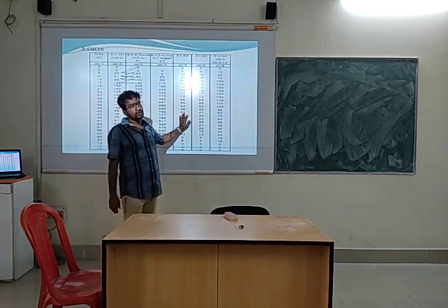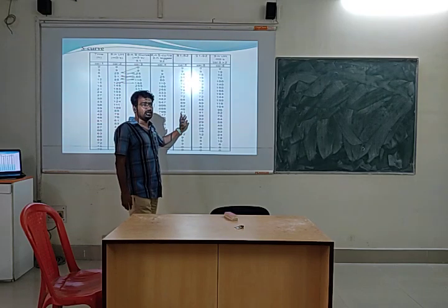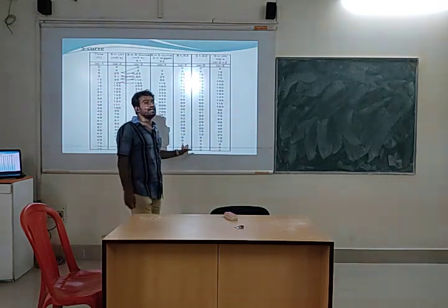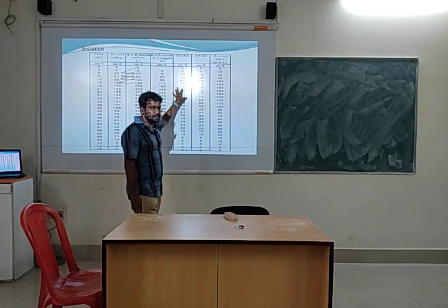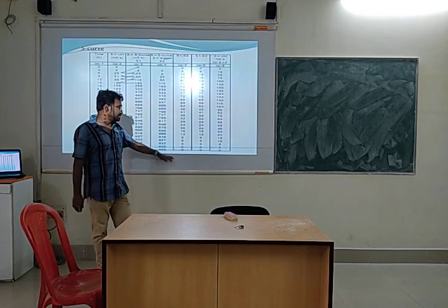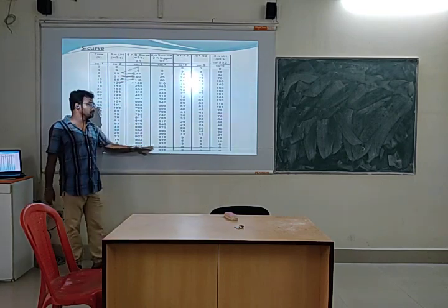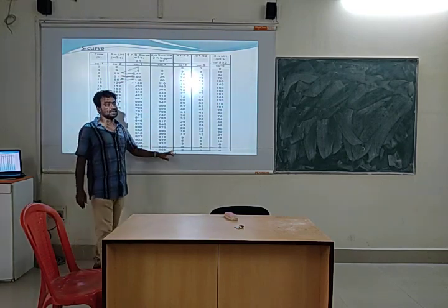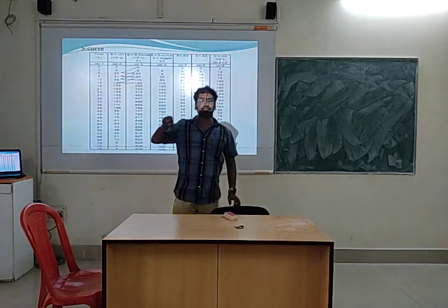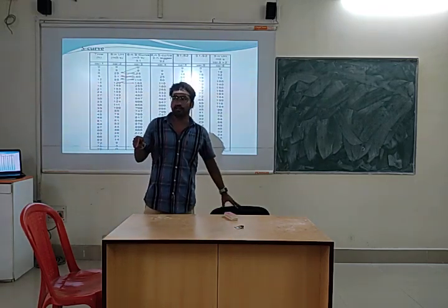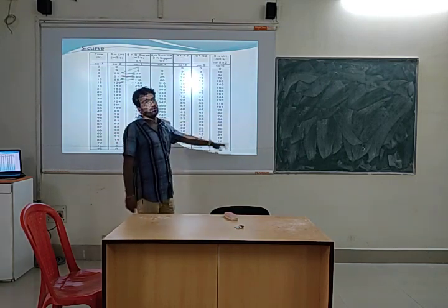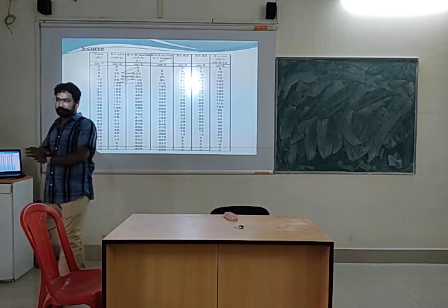Then you need to find the subtraction of S2 from S1. So you can get those values, S1 minus S2. You can simply subtract the ordinates. Then obviously after a certain time, both the values will be the same, that is why all the values will be zero, so we'll get the ordinates for the 3 hour unit hydrograph. But what you need to do after subtraction is multiply the value by D by T.